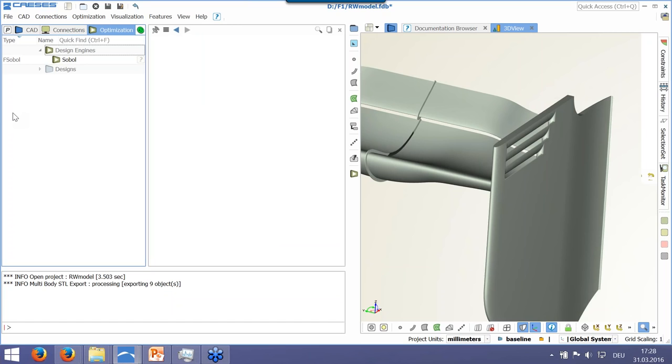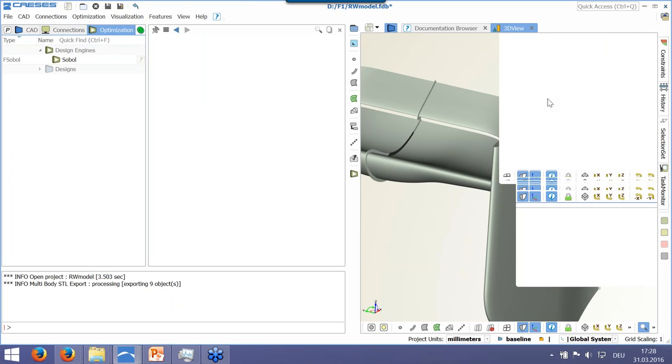Then there is a question about hardware requirements. What PC is suitable for SimScale, about optimal RAM and processor? That's a very good question. Basically, for using SimScale you don't need any specialized dedicated hardware. For sure, there are some minimal requirements, like a graphics card which supports 3D and WebGL. In general, we recommend a minimum of 2 or 3 GB of RAM, a modern CPU not older than 5 years, and a graphics card which supports WebGL.